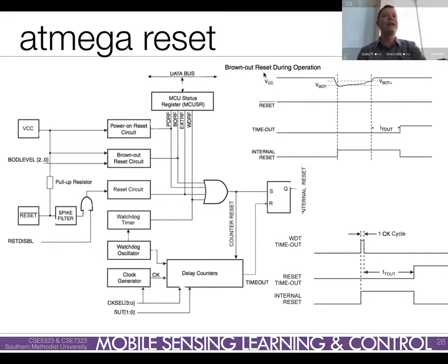And what you'll have is this. You've got a load on a battery, and the microcontroller's working, everything's working fine, and the battery starts to die a little bit, and essentially it dips down below 5 volts. The microcontroller will start to have things shut down on it that need to work on 5 volts. And when those things start to shut down, the load on the battery basically comes back up. And so the voltage on your battery pops back up. And all of a sudden you've got power and everything starts to turn back on. And now that everything's back on, it starts to really pull the voltage down on the battery.